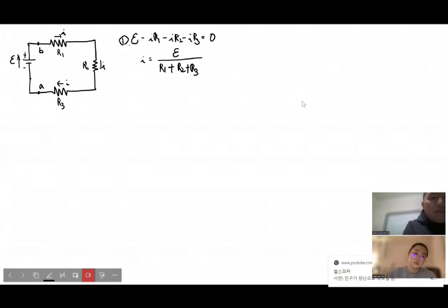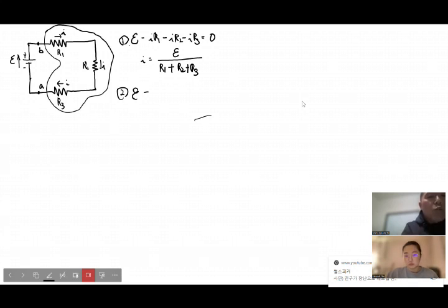And that is the same as if there's one gigantic resistor representing these three resistors. Then you can think of there being only one equivalent resistor attached to this circuit, A and B. In that case, that should be epsilon minus I R equivalent, which should also be the same as the potential increase out of the battery. So the current flowing out of this equivalent resistor should be the potential increase divided by the equivalent resistor R_EQ.